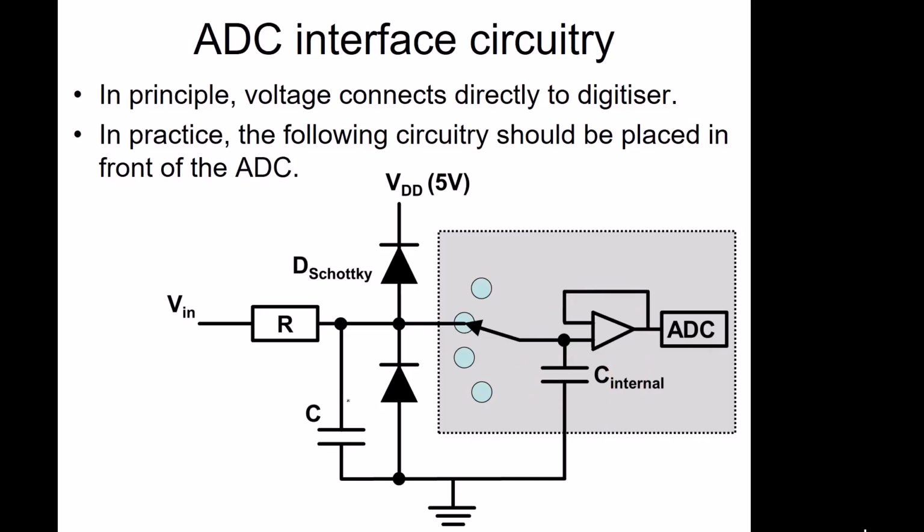To get around that, this capacitor that's used as your anti-aliasing filter is also forming a parallel capacitance with this internal capacitor. Provided this capacitor is relatively large compared to this internal capacitor, then any voltage that might be present on there when this multiplexer switches has little effect on the overall voltage at this point, because this capacitor is dominating.